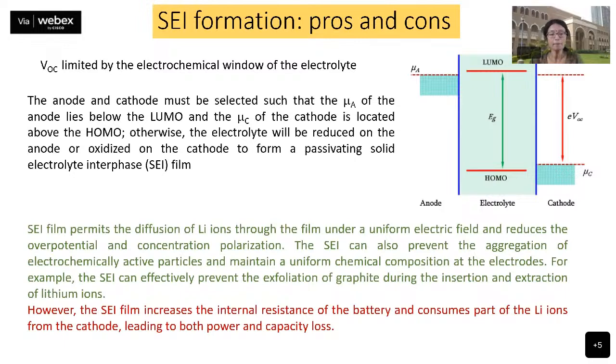So now what happens? We talked about this open circuit voltage. So you would say that, okay, fine, let me now just increase the anode chemical potential, decrease the cathode chemical potential, and then you will get a VOC which can be used. So you can just permanently keep on increasing, depending on the material, the voltage of your particular battery or your cell, but that is not to be.